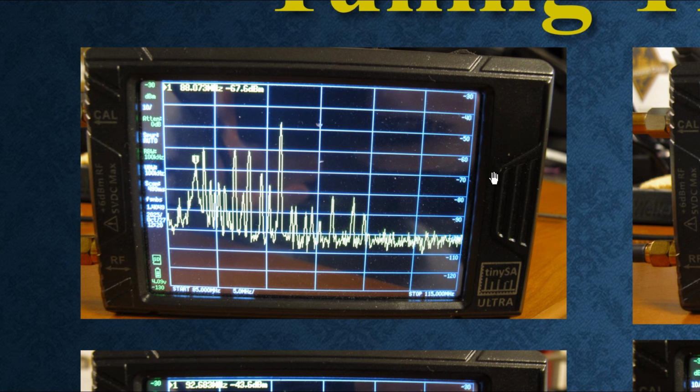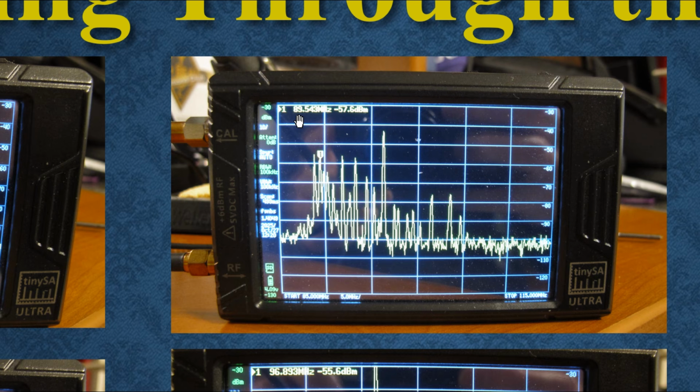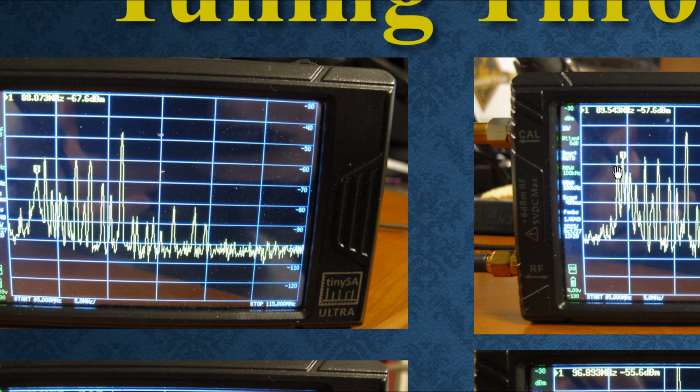Let's tune around a little bit more. This was at 88.1 megahertz. Here I've tuned up to 89.5 megahertz. That's where the marker is. And you can see that signal really pop up. Where was it before? Well, it was this guy right here. So now that one's being accentuated or amplified, and the one at 88.1 is now down here. In any case, the big guy has still not popped up very much. It's exactly what we want.